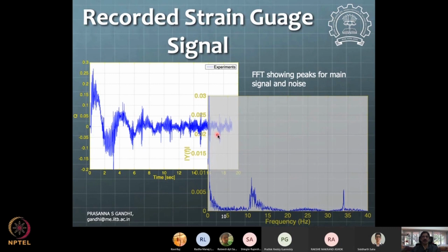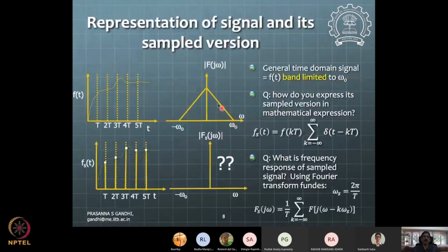Like that, one can see the actual signal in a similar way as we have seen. You can see that the signal is in no way like this triangular representation at all. For the sake of mathematical completeness, you actually define this on the other side also. When you get into the proofs, you'll see that this part is actually needed to be considered. That comes mainly from the mathematical precision of the discussion. This part has no real physical significance. A negative frequency will not have a physical significance at all, but for mathematical completeness it needs to be considered when you do further analysis.